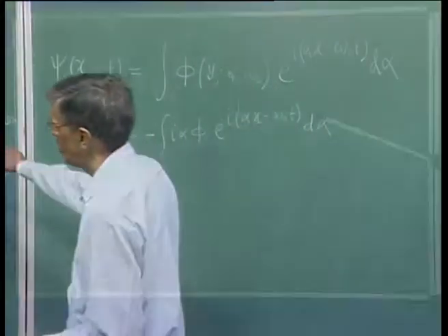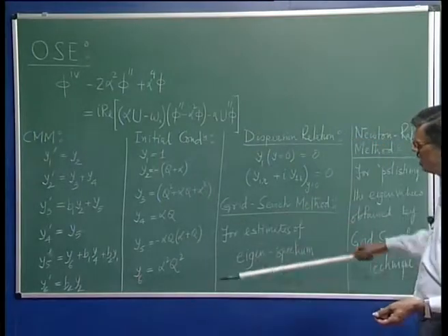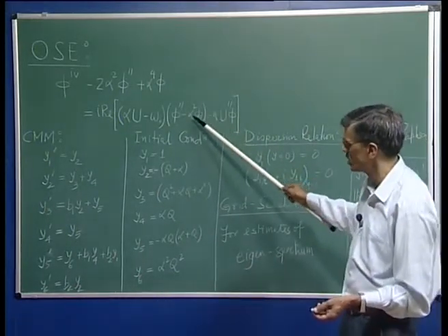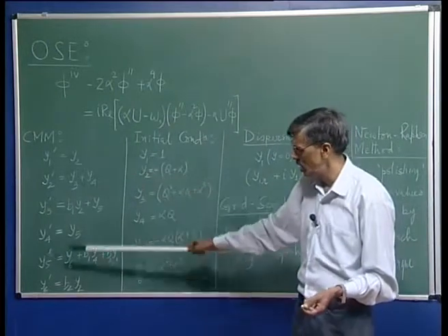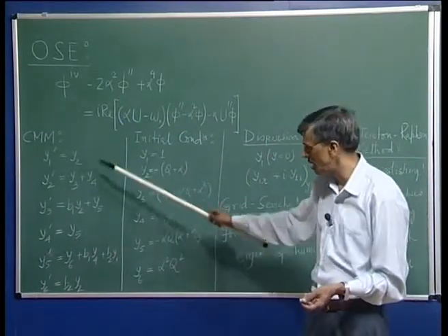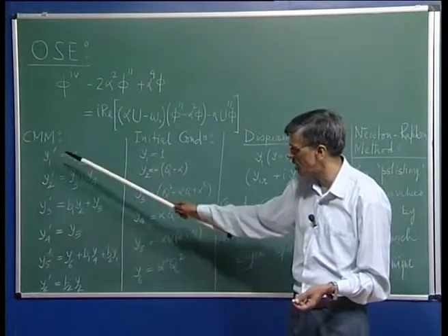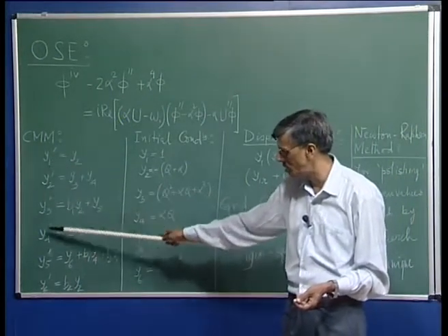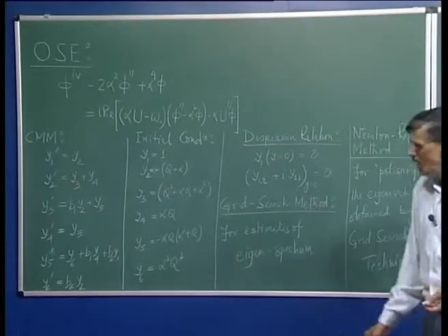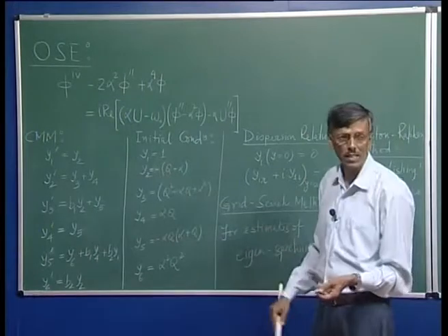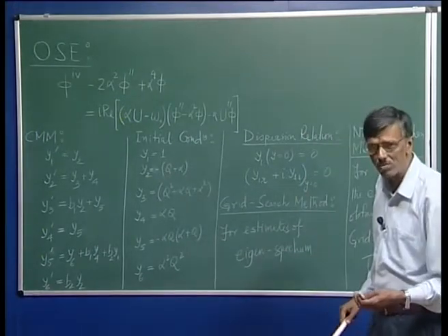So, that is what we need to keep in mind, and what we did was that we noted this was a stiff differential equation. We converted them into this set of 6 first order coupled ordinary differential equations for the compound matrix variables y 1, y 2 to y 6. And these variables have the property that they satisfy the free stream condition.